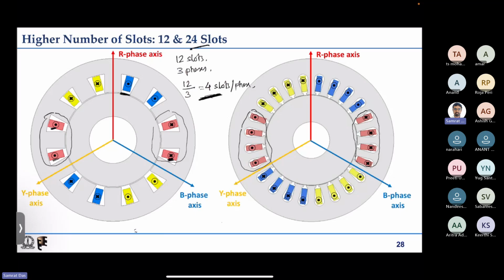We have two poles, that is two iron regions, and in between we have a slot, which does not have any ferromagnetic material, so it has higher reluctance. Because of that, the flux density is quite low in this region, and we'll have a better look at it as we go ahead. But you can understand why the dip in between is coming.